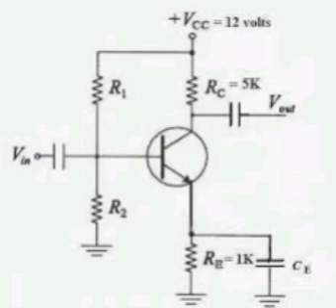In the circuit shown in the figure below, M1 serves as an electronic switch. If Vin is very small, determine the W by L such that the circuit attenuates the signal by 5%. Assume Vg equal to 1.8 volts and RL equal to 100 ohms. Mu n Cox equal to 200 microamperes per volt square and VTN equal to 0.4 volts.